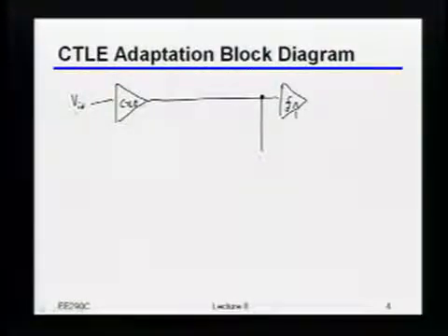It's basically an FFT engine, but just a 2-point FFT. Oh, okay. You could actually do an FFT. By the way, remember I want simple and low power. So I think I need the ADC and the FFT. So I guess you're right. A 2-point FFT is not so bad, but I think I can do it with less overhead than that. But that is indeed correct. Well, there's another minor caveat, which is my signals aren't guaranteed to be periodic, but we'll ignore that too.